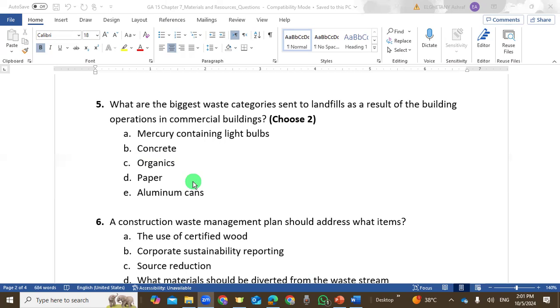But in real life, and when you finish also LEED BD+C, LEED AB, the second level, we do waste audit. What is a waste audit? I will go to this mall, or a factory manufacturing dress or clothes, and see what types of waste. Of course, I will find clothes in the waste, and also any equipment related to clothes. So it's not glass. It's not plastic. It's not metal. So I will make a waste stream named clothes, and plan how to recycle these clothes.